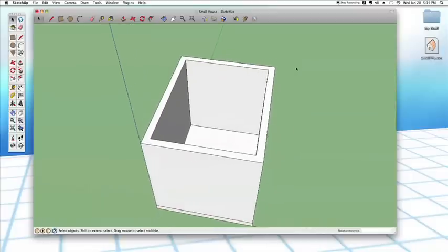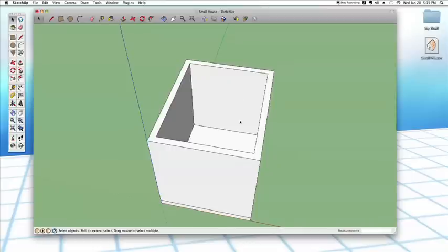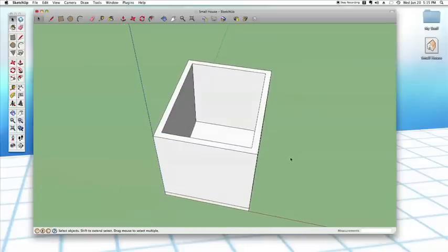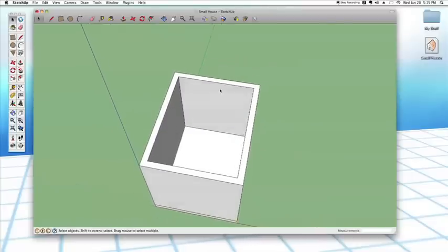So what I like to do instead is just think of that before I actually start modeling my room. If I think, okay, I want this to be an 8-foot by 10-foot room, remember just to add 6 inches to all 4 sides, or 1 foot on one side and 1 foot above. So instead of 8 foot by 10 foot, I would have drawn this at 9 feet by 11 feet. And then I would have gotten an 8 foot by 10 foot dimension on the inside. But in this case, 7 feet wide is actually just fine, although it is looking not exactly long enough. It's looking a little bit short. I'd like this to come out more.